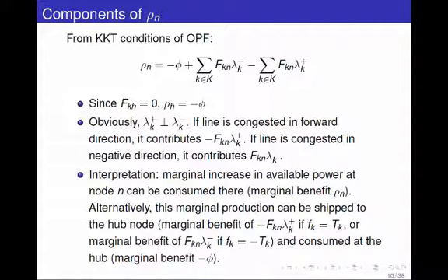Do you have any intuition about why that's the case, based on what I described here? Maybe it cannot be full in both directions. Exactly. If it's hitting the limit at 100, it's a positive flow. It's not going the other direction. The other way around, if it's hitting the limit, this line has a limit of 100, whatever the direction of flow is. So it can be hitting it in the up or the down direction. If it's a negative flow, then it can't be a positive one. So I know that for each line here, either one term is contributing or the other.